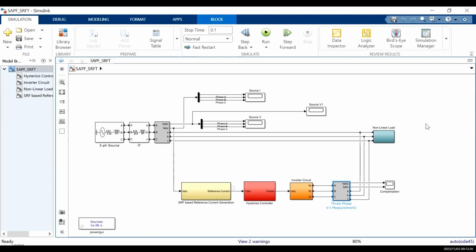3. Variable frequency drives, VFDs. Three-phase VSIs are commonly used in variable frequency drives, enabling the control of motor speed and providing soft start and stop functionalities. VFDs find extensive use in industrial pumps, fans, compressors, and HVAC systems.